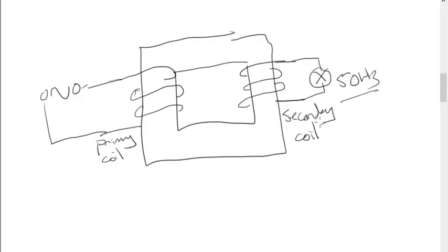So similarly here, what happens is if you increase the number of turns in the secondary coil, it's going to increase the induced EMF. So say the primary coil in this case has 100 turns, and the secondary coil has say 200 turns. So then what will happen? The induced EMF will obviously double.